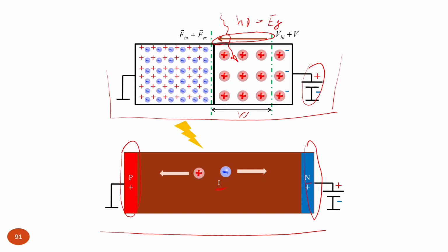So in that case, when we apply external bias, we create a strong electric field in all this area of intrinsic semiconductor, and that means in a wide range of thickness of the intrinsic layer, which can be much thicker than the depletion layer of a PN junction, we have efficient separation of charge carriers. So we can apply large biases and get efficient extraction of charge carriers. For photodiode characteristics, that's really nice.